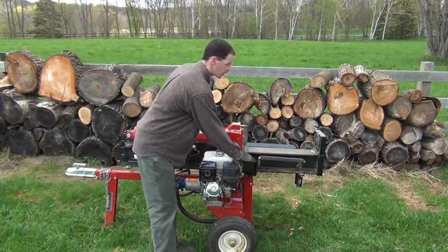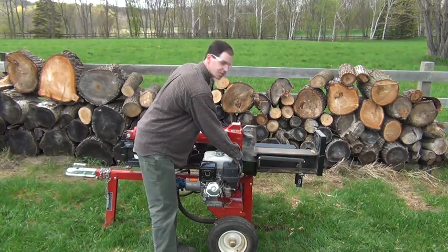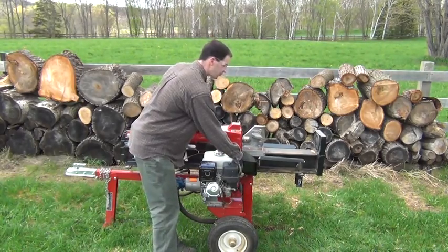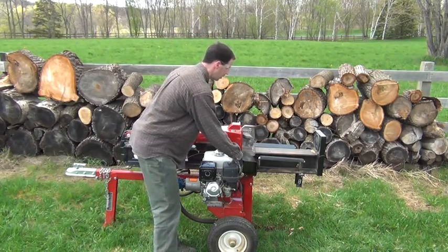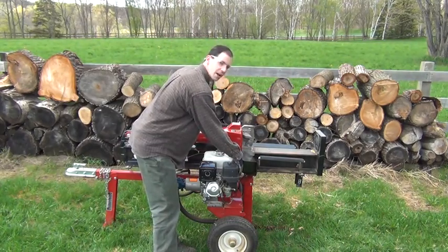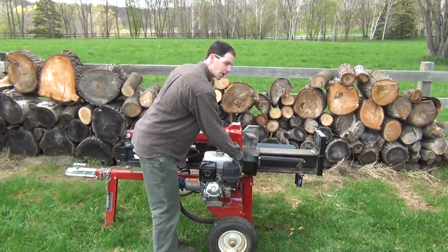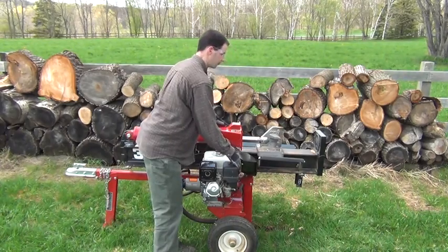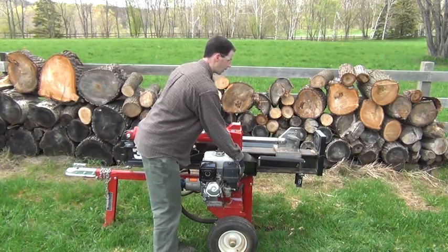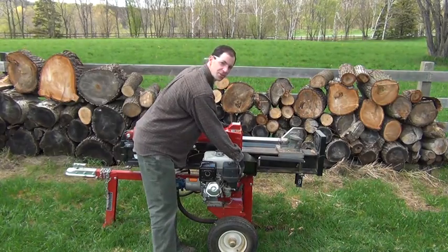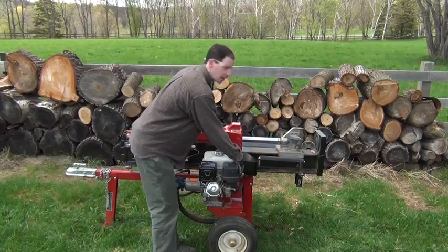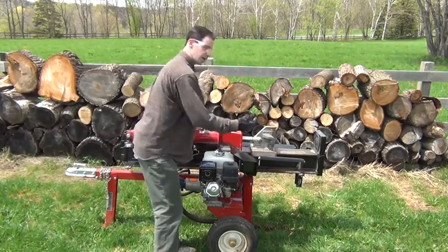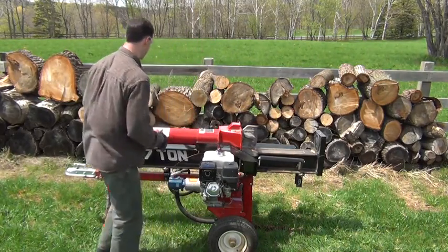So first I'm going to run this at low idle, and this is our extension speed, fairly slow. This is our retraction speed. You'll notice it's a little bit faster. And now let me run this in extension, but at a high speed. So this is our low idle, and now let me increase the engine speed and therefore the angular velocity. You'll notice that the piston speed increased greatly. And the same thing is going on in retraction. And if I increase the engine speed, it'll speed up as well.